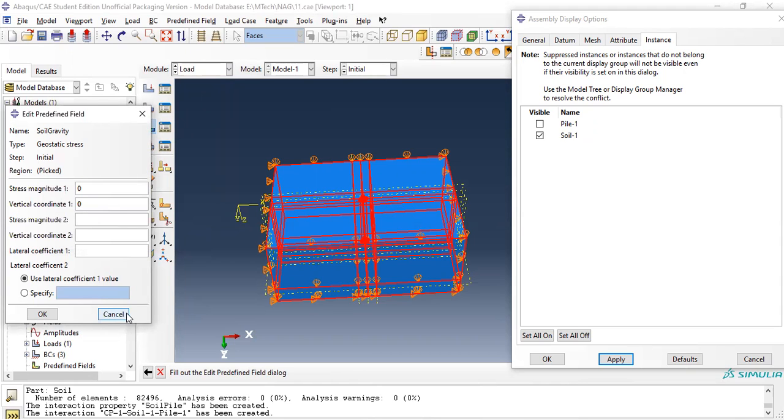Let's take the density of the soil as some minus value. Minus is because z is towards the downward direction. Suppose it's 1700 something. So that is rho, the density, times g, g is 10, times the z value. The z value is 25, the vertical coordinate.